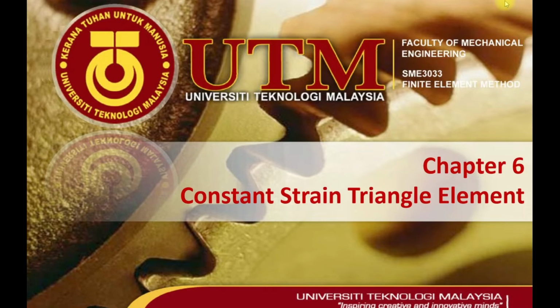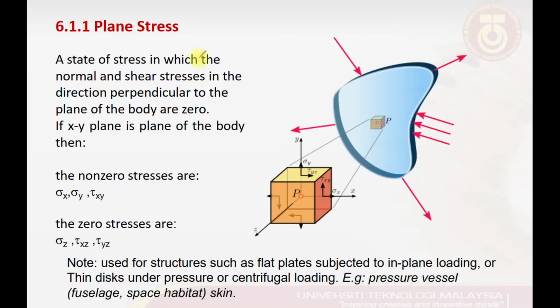So in this lecture, we will look at models that can be used to deal with this kind of problem, and also to see under what conditions we can apply them. So the first model that we are going to consider is known as the plane stress model. This model is a state of stress in which the normal and shear stresses in the direction perpendicular to the plane of the body are zero.